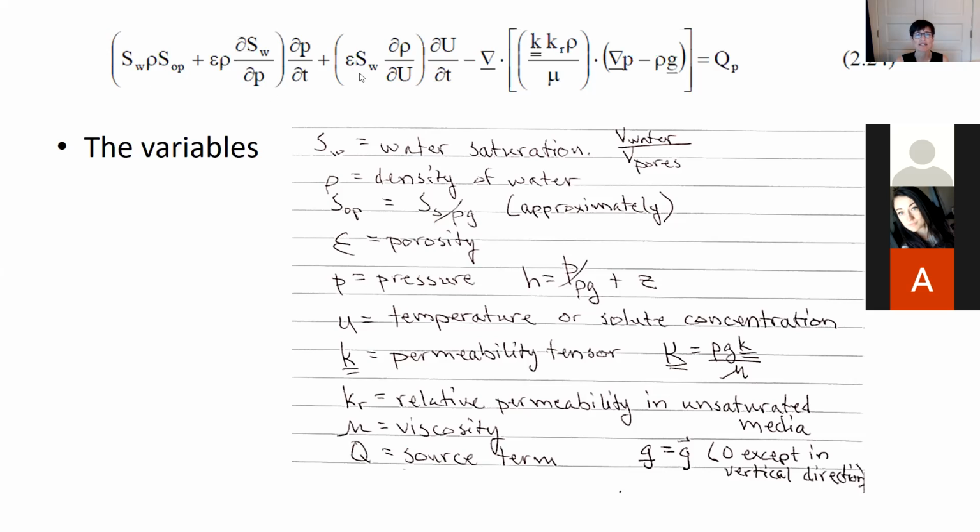All right, what's this next one? We've got the porosity times the water saturation. If you're thinking about doing a mass balance and you want to know how much mass of water is in this pore volume, you need to know what the porosity is, and then you need to know how much of that porosity is occupied by water. That's why you're seeing the water saturation show up so much. And in this term in particular, what's the mass of the water here? Now, the issue is that the density of the water can change with time. So this is the change in the density because of something.